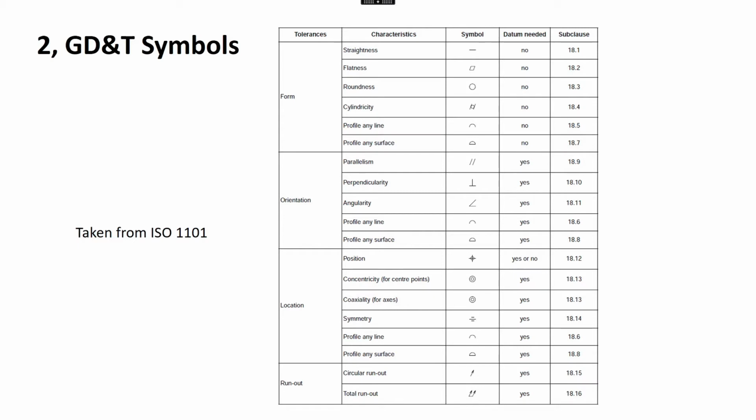So it's no good just the pattern of holes being relative to themselves. They usually want to be relative to the face that you're drilling in as well. So it's always really recommended to put that datum A in there as a very minimum. So that's what I would do nowadays.